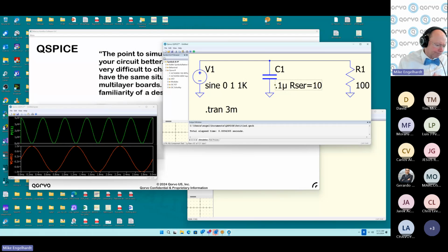The problem with the way I've done this with passive components, plotting the dissipation as the power flowing into the device, is that a lot of times the device would put power into the rest of the circuit. Like if an integrated circuit has capacitance on the pins, and those pins discharge into the circuit, the IC is creating power. And besides being confusing, it simply isn't the quantity you want.